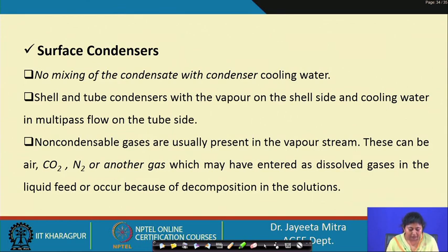Also, with the vapor there are usually some non-condensable gases present. This can be air, carbon dioxide, nitrogen or another gas which may have entered as dissolved gases in the liquid feed or occurred because of decomposition in the solution. So, these have to be removed from that vapor.